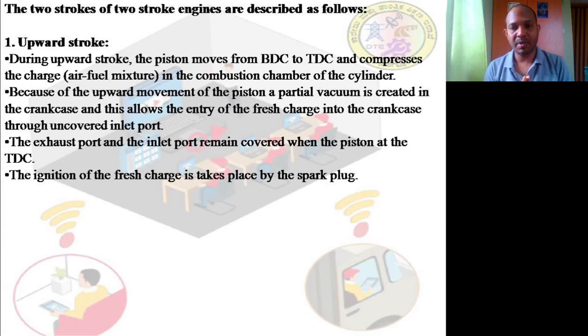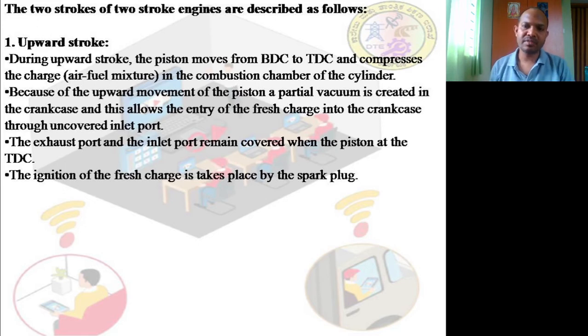Now, one more important thing is ports are something like a passage, that's it. There is nothing called doors. Valves are different. With valves, if you want you can close it, if you want you can open it. They are something like doors. Ports are something like a sliding window. Whenever the piston moves this way, it closes. Whenever the piston moves this side, it opens. That's it. Are you getting my point? Ports are something like sliding windows, whereas valves are something like wooden closing and opening windows.